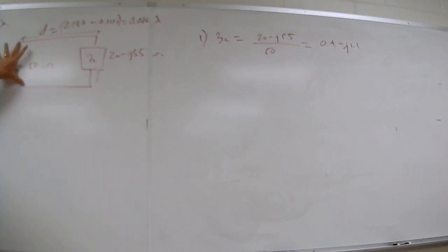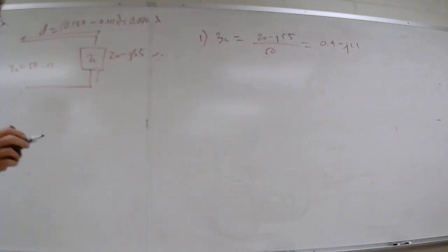Now, the normalized admittance right here is this value, right? That's admittance. Now, did he say in shunt? Yeah, admittance. So we're going to add a transmission line that's going to have the opposite value, minus j2, as the input admittance. Y'all hear me on this? I'm going to draw it over here so you can see it.